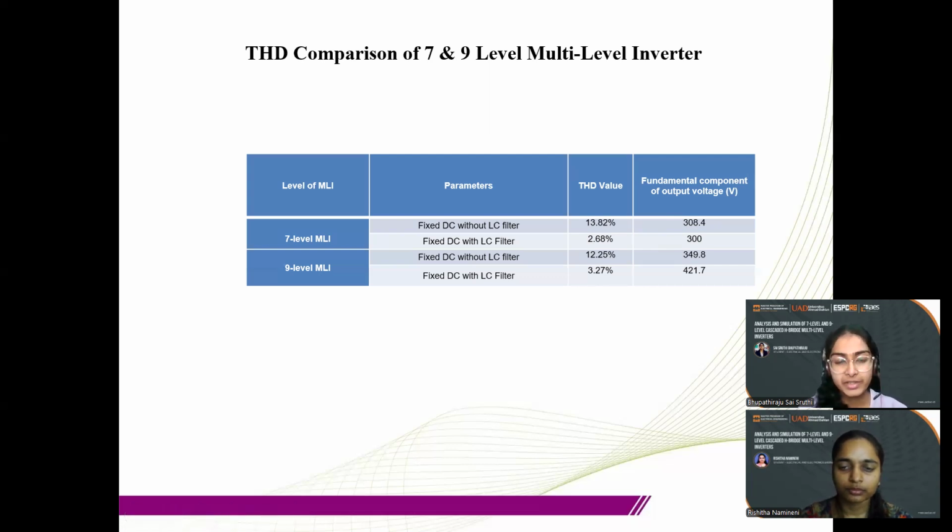By all these observations, we can conclude that the cascaded H-bridge multi-level inverter produces better quality waveforms than conventional inverters. While working with inverters, PWM techniques are essential to achieve the desired output. Upon considering various factors, it was decided to use the level shift pulse width modulation (PWM) technique for this project.